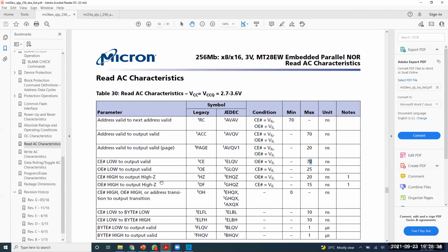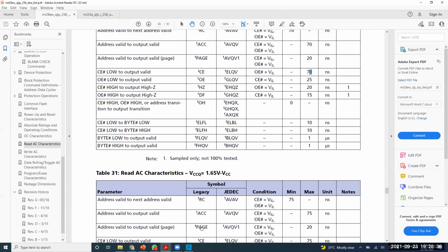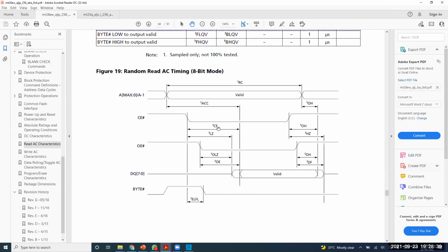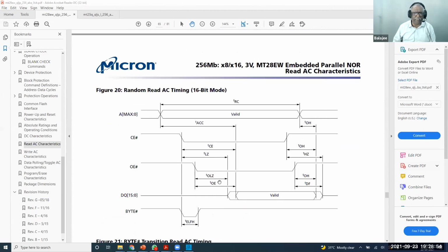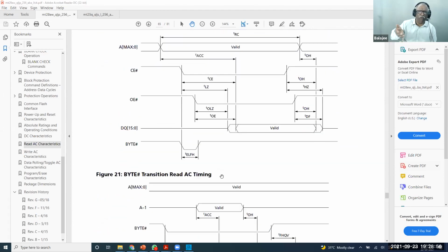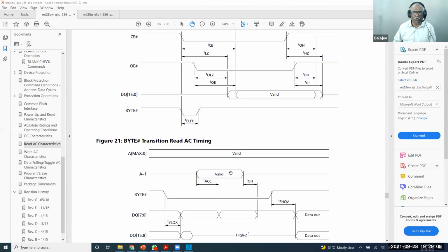So for every timing diagram, you're supposed to follow this. What we do is verify with a logic analyzer. We will check these wires, and the logic analyzer will show this diagram. We will compare with this. Understand? So these are all the timings you're supposed to meet. This is the job of a hardware engineer. But nowadays, this job has come to software because all the timings are programmable in the chip. That means you can do anything.